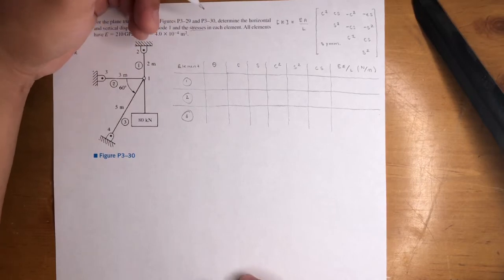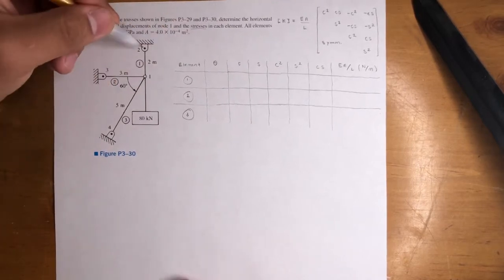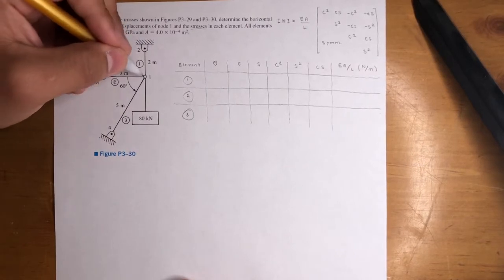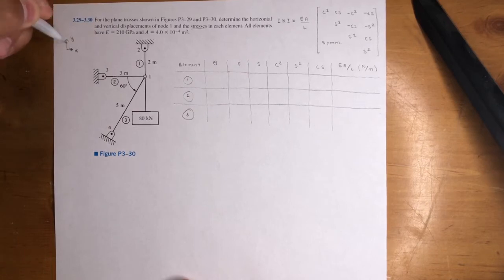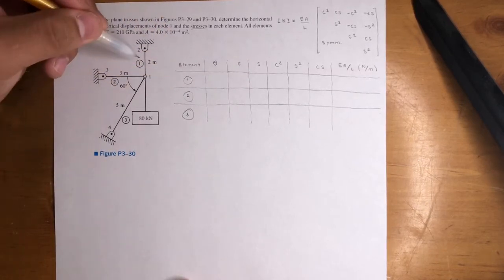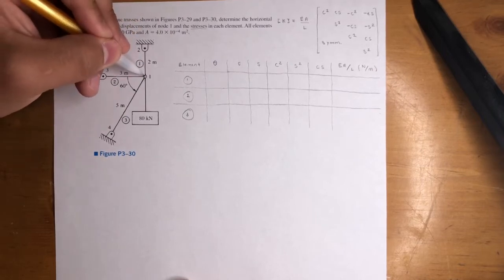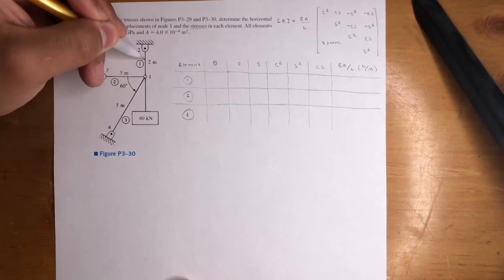So you'll see. Determining the angle, I mentioned it in the other videos, but moving forward, I'm just gonna mention it every single time. So you know there's the positive X direction, right? And we want to find an angle to kind of characterize each beam. I always like to start from the small node to the big node. In this case, for element 1, we're going from 1 to 2.